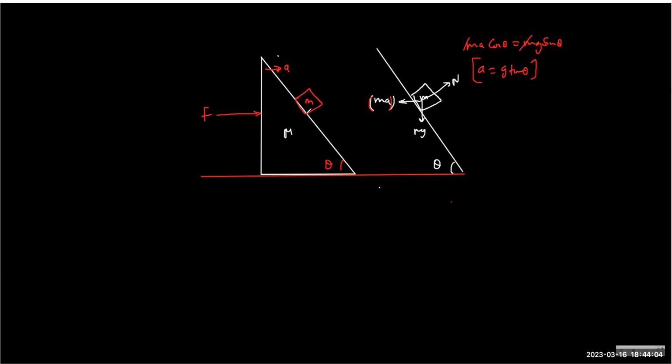Now the same question I am changing here. I have brought friction here. The actual force applied by the surface in this case is normal and friction, both. So now what is happening? The moment you introduce mu s, if you push the wedge very hard, the block will skid up the plane, right? And if it is very slow, then it will go down the plane.